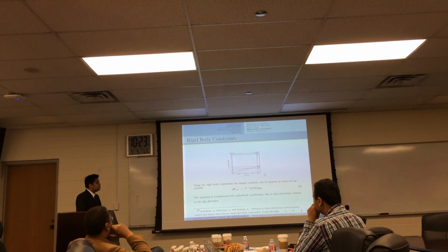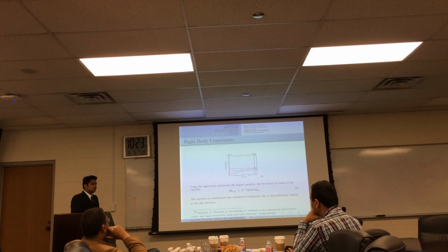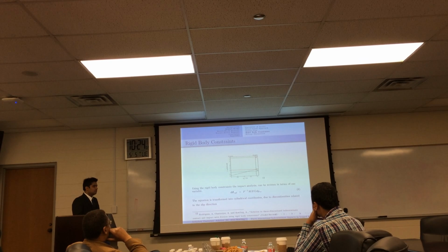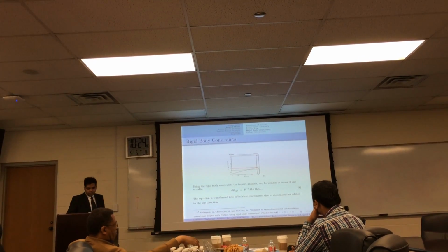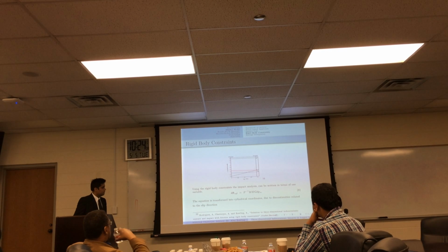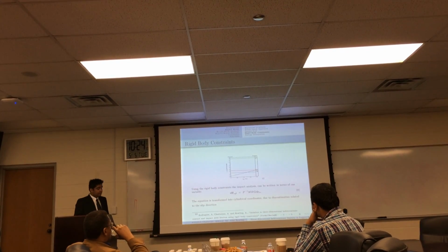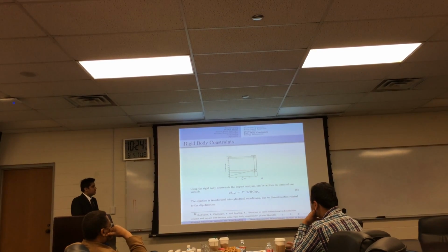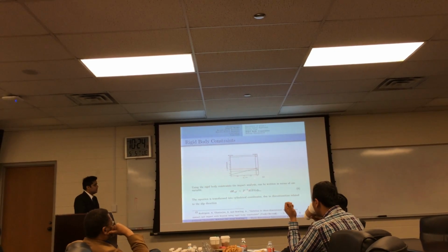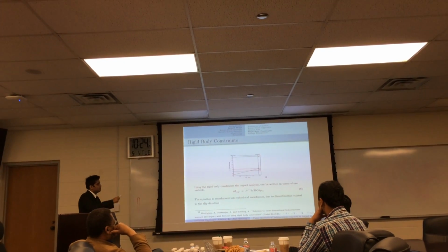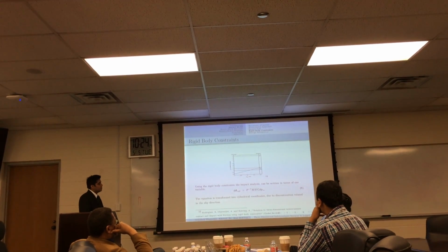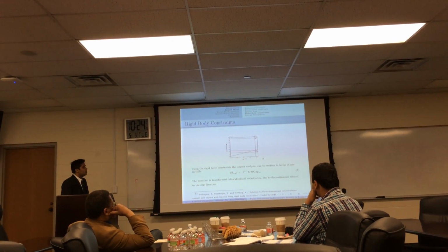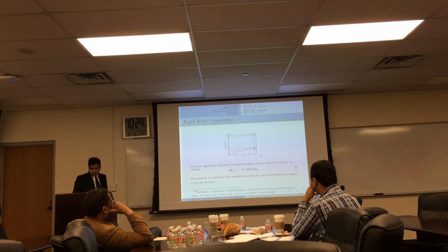We would essentially try to describe all the velocity in terms of cylindrical coordinates. And P inverse over there is a transformation matrix that converts the Cartesian coordinate velocities into cylindrical coordinate velocities. And then at this point, if we evolve the velocities with respect to impulses, we would be able to get a plot like this, where S is the sliding velocity, phi is the sliding direction, and Vn is the normal velocity.